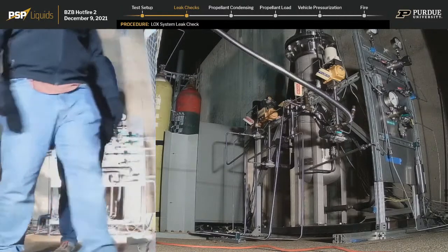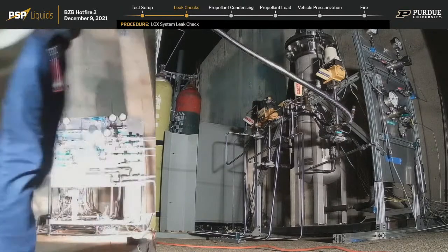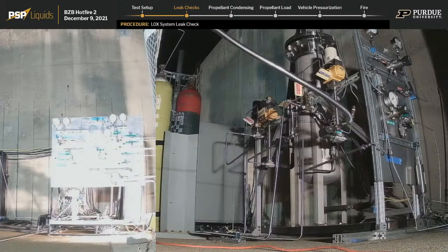So what goes into having an accepted leak rate versus a leak rate we reject on a certain system? It's kind of go at the pace of the system. We have a total acceptable leak rate for the system defined as what we think is safe for us to operate with. When we leak check with nitrogen, we're able to do this in a safe manner and make sure that when we actually get to the phase of the operation where we're loading propellants, all operators are behind solid cover. Now you just heard a call out for operators going behind solid cover. When we fill the system...